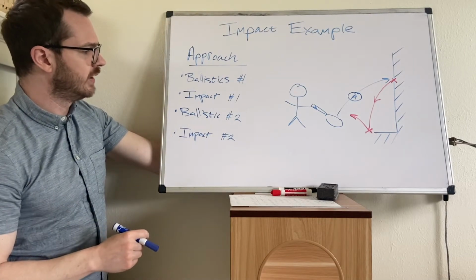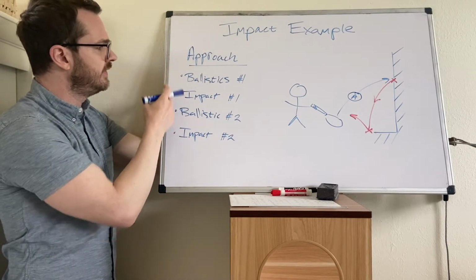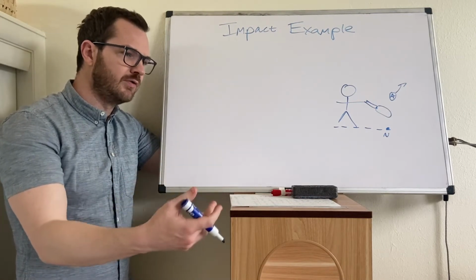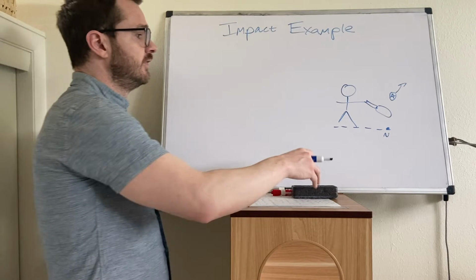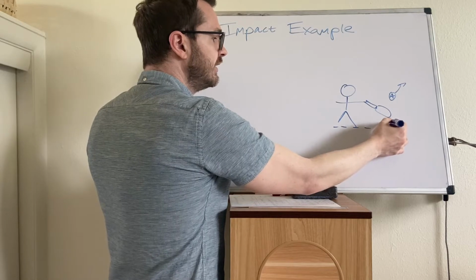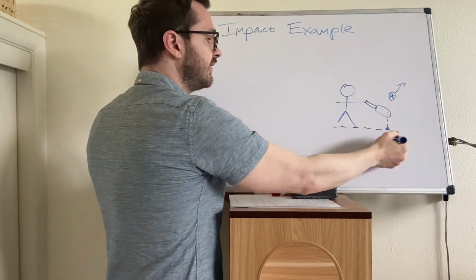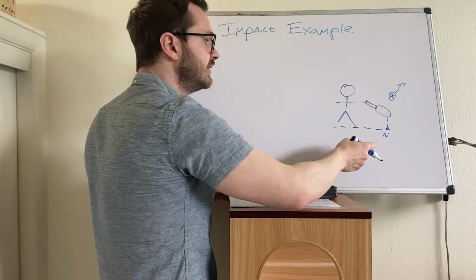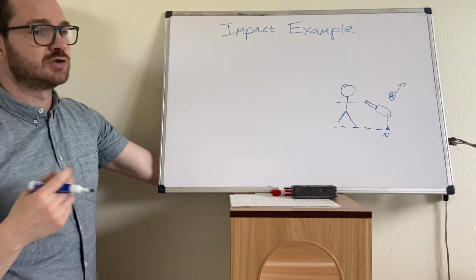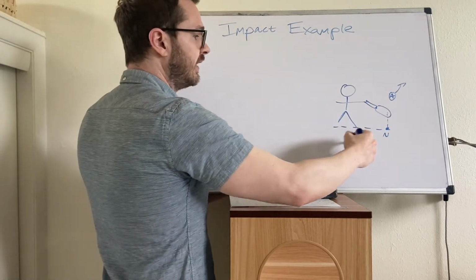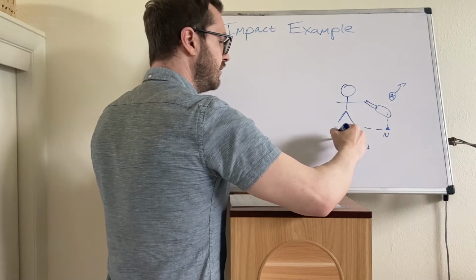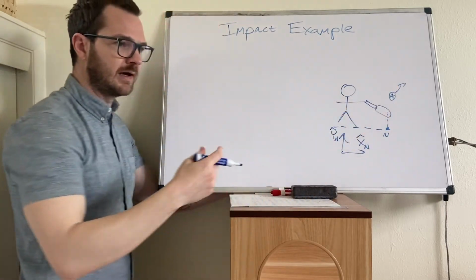Okay, so where do we need to start? Well, let's take care of these ballistic phases first. To resolve this ballistic phase, we need to do the kinematics, we need to do forces, and we need to do the equations of motion. So let's put an inertial point in. I'm defining point in underneath the racket, such that the x-coordinate of the initial condition is conveniently 0, and then there's going to be some vertical component in its initial height. And of course we need some inertial frame on this problem, so x in, y in, and let's treat body A like a particle so we don't have to put body frames on it.